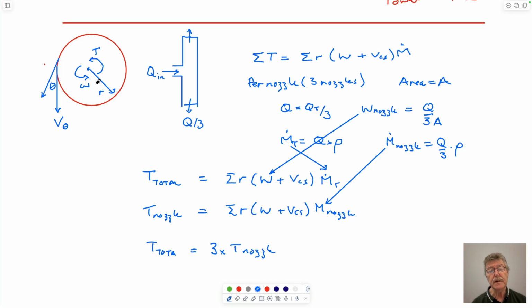So the idea that this comes in is that this is almost like an unsteady problem. This is almost the gas cylinder. This water is suddenly arriving in here and it comes from nowhere. It doesn't come across a control surface because the control surface it's coming across is here, and we're not accounting for that because we're not resolving in that direction. We're only doing it rotationally. But we need to have these components in there.